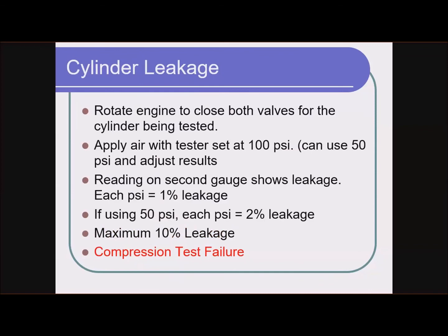It requires you to put the engine in specific positions for each cylinder. So if you have an engine that things are difficult to get to, you don't want to do a cylinder leakage test just for kicks. The best reason to do a cylinder leakage test is this. You've done a compression test and one or more cylinders have failed.